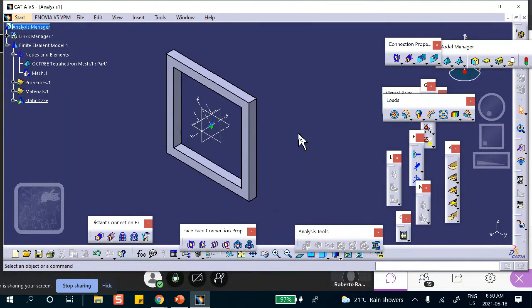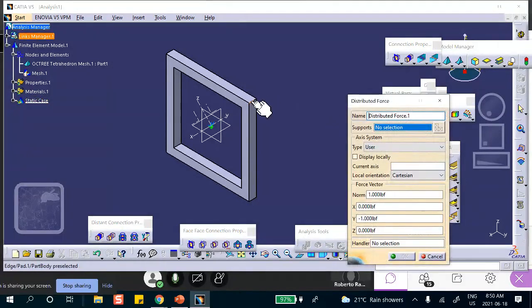Now, we're going to apply loads. Okay, load. There, force, right there, force. On that edge. In the direction negative y. Negative y, like that. Negative y. User coordinate system, see that? User, ordinarily it's global. I don't want global. I want user. I created this because I want to use it. So user, and it's waiting for you to go and pick it.